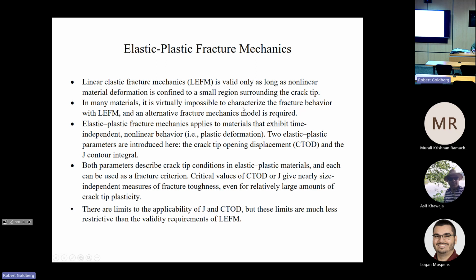And for many materials under high enough loading conditions, it's impractical to use linear elastic fracture mechanics to characterize the fracture behavior. Thus, alternative models are required. So what we're talking about here is nonlinear behavior, but time independent, i.e. under the constraints that satisfy the rules for classical plasticity. We're not going to go into viscoelasticity or viscoplasticity type of approaches.